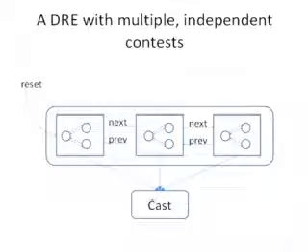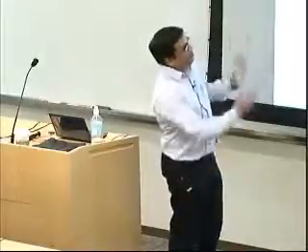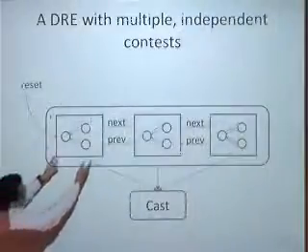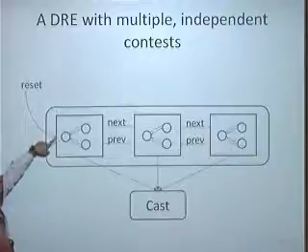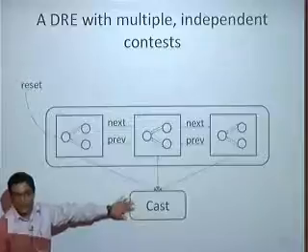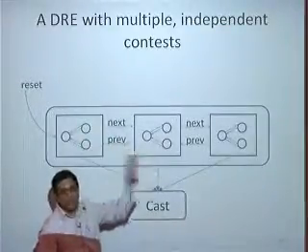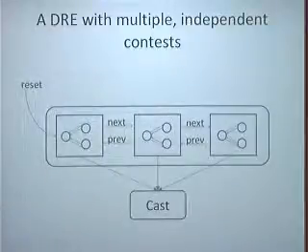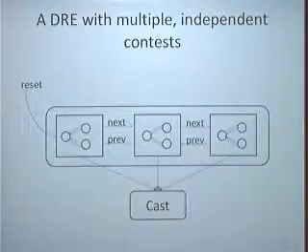Okay, all right. So now, the structure of the machine is as follows. It's similar to the specification voting machine that I showed you. For each contest you have a state machine. When you press reset, you start at the first contest. From any of these contests, you can press cast and end up in the cast mode, or you can press next and previous and navigate between contests. And as you see, it has a similar composition structure to the one we had in the specification voting machine.